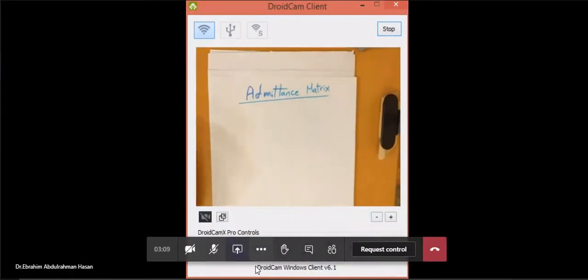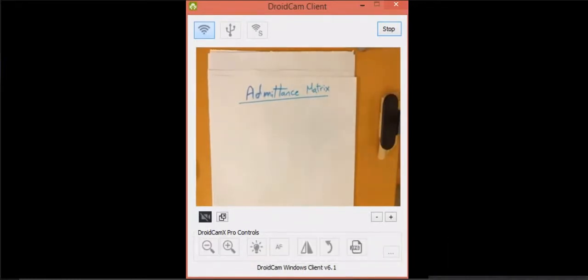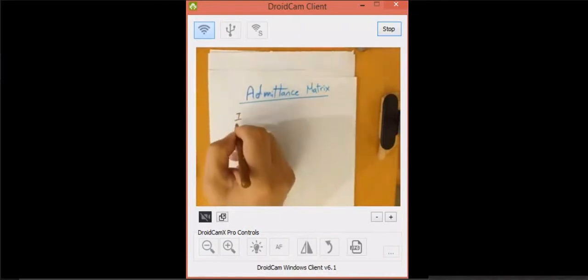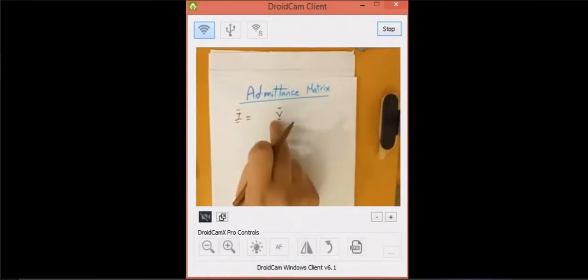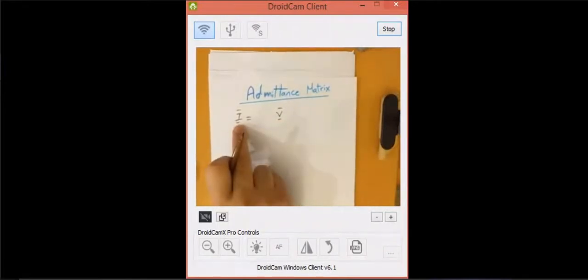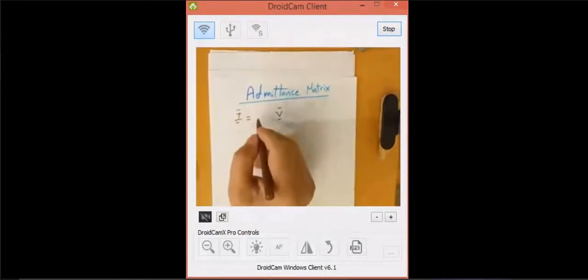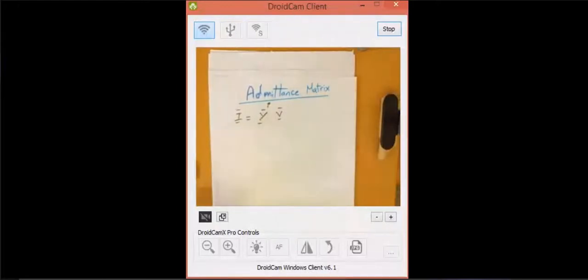Okay, so today we are going to talk about the admittance matrix. As we define, if we have a vector of I, and here we have a vector of V, the node voltages, and I is the injected current in each node, then the matrix here we call the admittance matrix, Y. So we are looking for this one. How do we find Y in a very fast method by using nodal analysis?